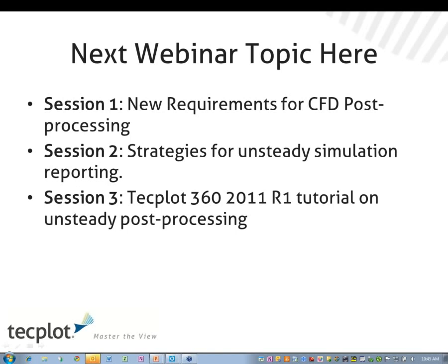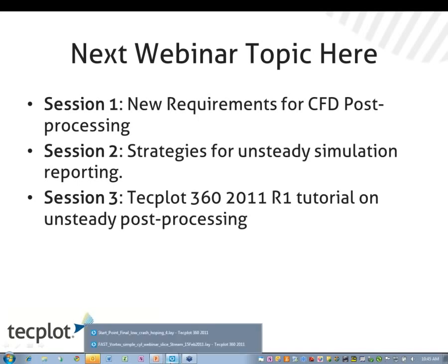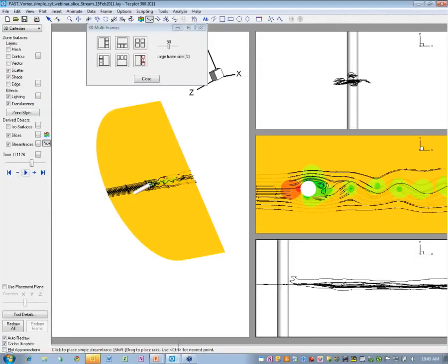There was a question about the accuracy of the calculation scheme on vorticity. It's slightly different with ordered and unstructured grids. With ordered grids, it is second order accurate center and time differencing for the velocities. And with unstructured, it uses a moving least squared scheme. Actually, I think it works out to third order in space.